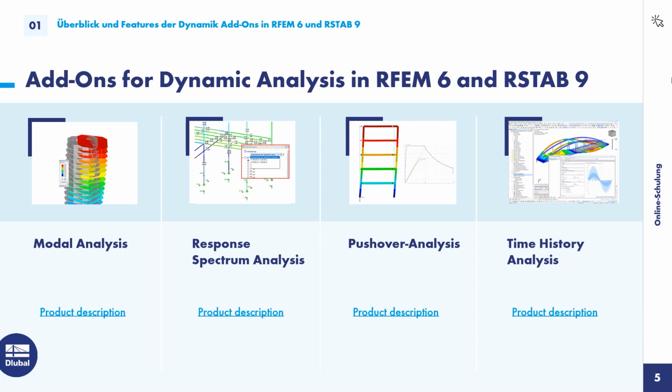Also, the time history analysis is not earthquake only, just like the modal analysis. It can be used, for example, for vibration designs and for general investigation of the structure and its behavior. You can also see on the right figure here, in the last webinar, I performed a time history analysis on a footbridge and investigated the acceleration limits.